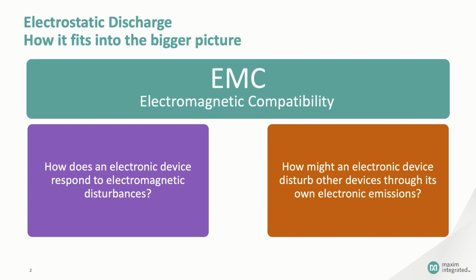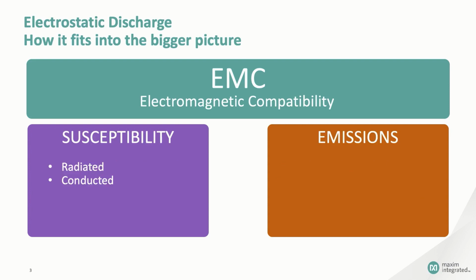Most frequently, we study how a device responds to radiated energy and conducted energy over a range of frequencies, and how much energy a device radiates as radio waves and launches on attached conductors. Frequently, we'll look at a specific type of conducted energy known as electrical fast transient, or EFT, and that's a particularly difficult kind of conducted interference that's caused by some fluorescent lamp fixtures and other electrical equipment. Modern microcontroller-based devices have to be able to tolerate this kind of interference without damage and without resetting.